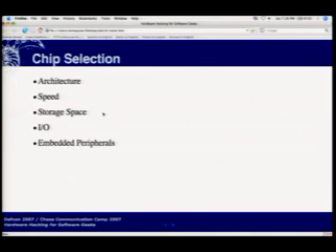A few notes on architecture. With a lot of the smaller microcontrollers, you have your choice between 4-bit, 8-bit, 16-bit, and 32-bit. Now the biggest difference between these, other than register width, is cost. And a lot of it is also speed of the processors. With a lot of the lower end 16 and 8-bit stuff, you're going to max out around 40 megahertz, and your onboard flash and RAM is going to be less than a meg combined.